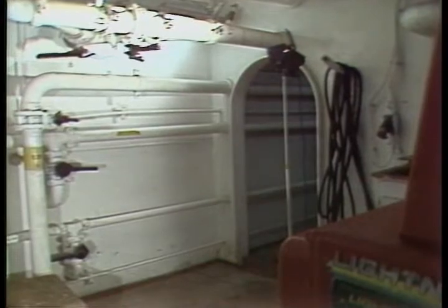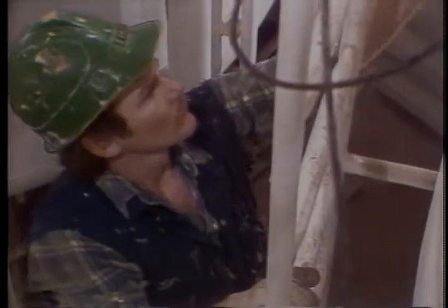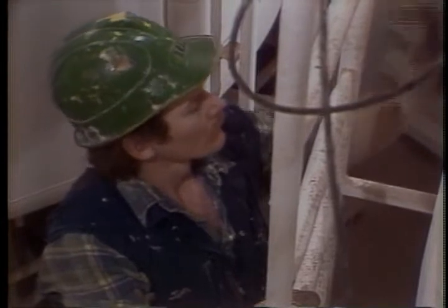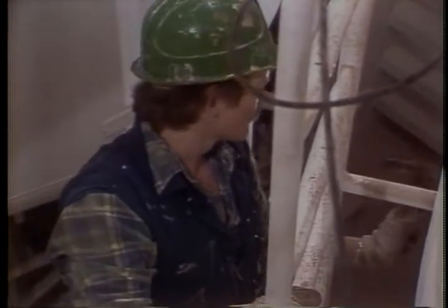The term comes from the old technique of determining the bulk levels of these tanks. The derrick man simply pounded on the tanks until the dull thud turned into a ringing sound. Then the number of steps were counted up to that level. Each step is about a foot, and the level was recorded. On some rigs, this technique is still used, but it's not all that accurate, and it could damage the tank, so we don't recommend it.